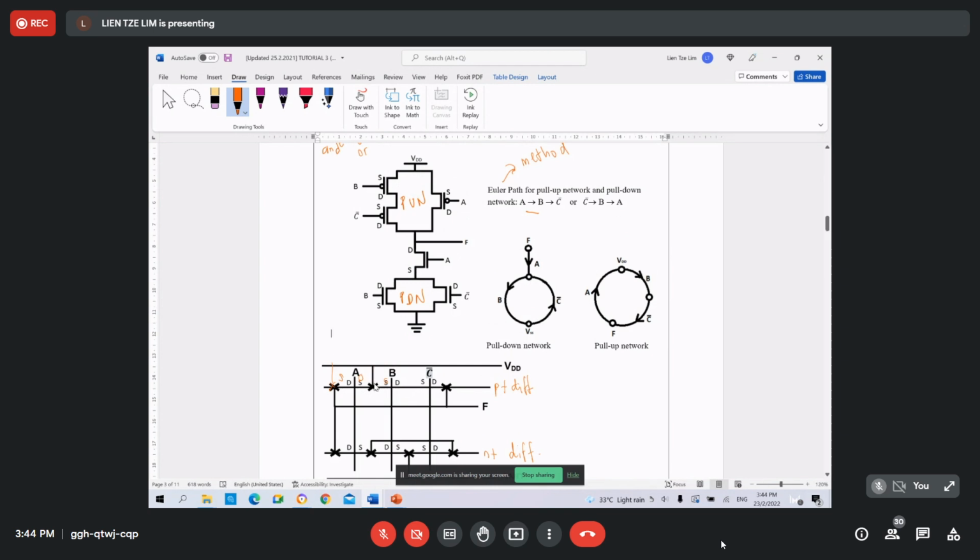So we want to optimize the use of the contact, and also minimize the signal routing or the wire. We can put them together at the same terminal, meaning only one wire to the same terminal for both transistors. So the source terminals here, we can label both here and to the same point, which is to the VDD.